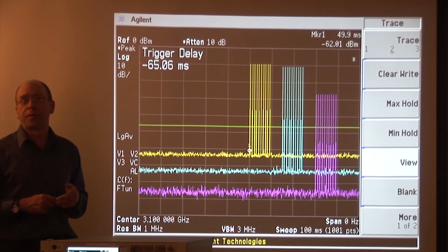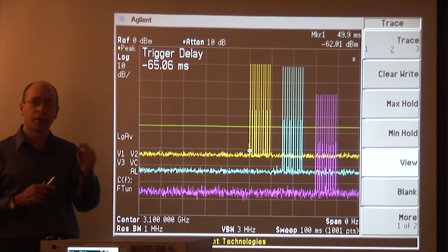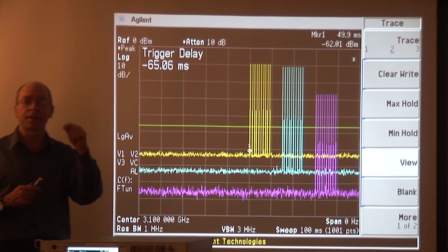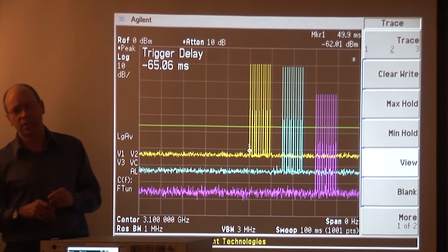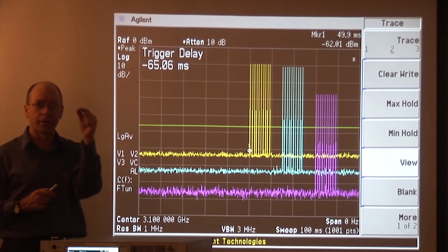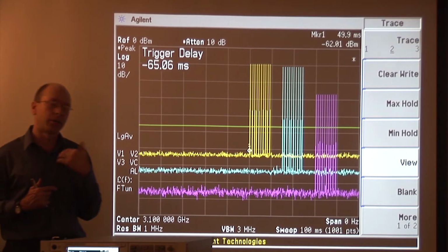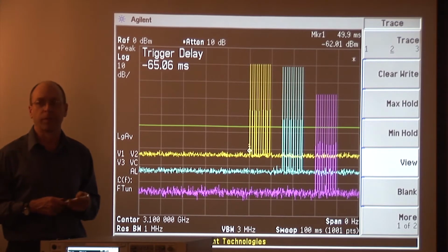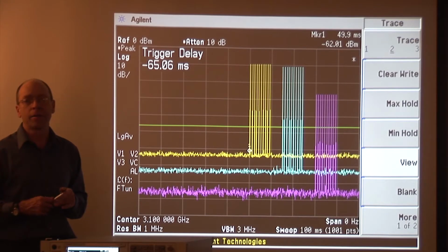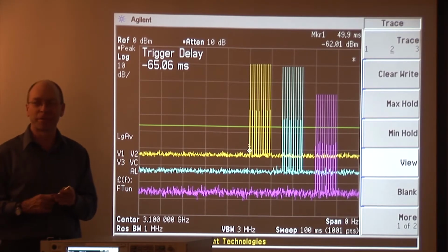And in fact, for NTIA's purposes, as far as I've ever been concerned, if the spectrum that we're measuring comes within a dB or maybe even 2 dB of the mask, we'll say that it's meeting the mask, because we recognize that we have an uncertainty ourselves of maybe a dB, maybe 2 dB in the measurement that we're making, and we're not trying to hold someone to that last dB. And usually they either meet it by quite a bit or they don't meet it by a lot. It's usually not a photo finish.